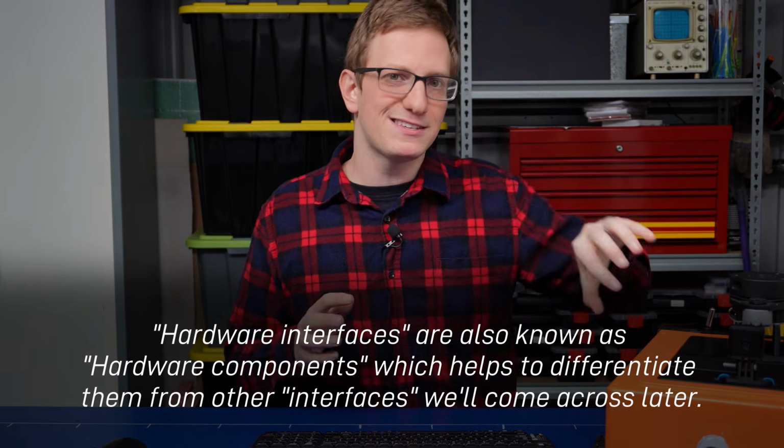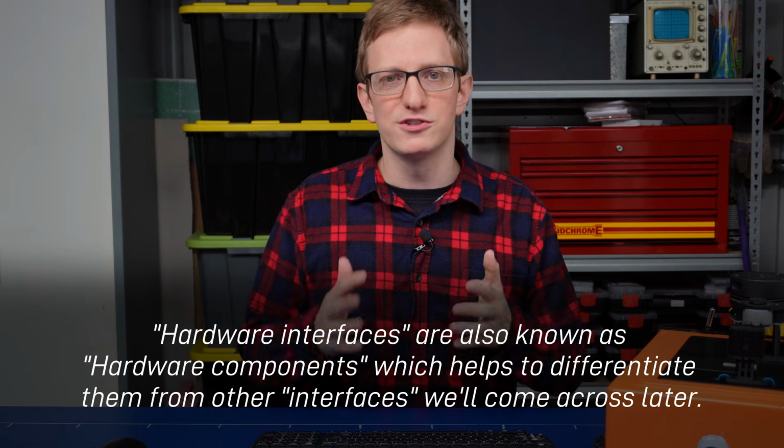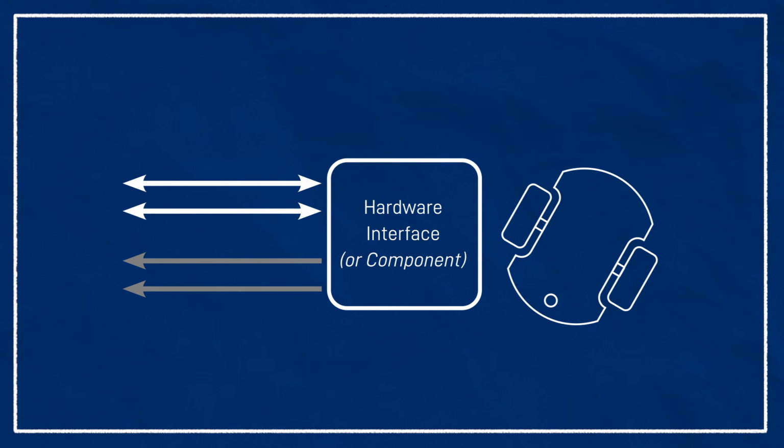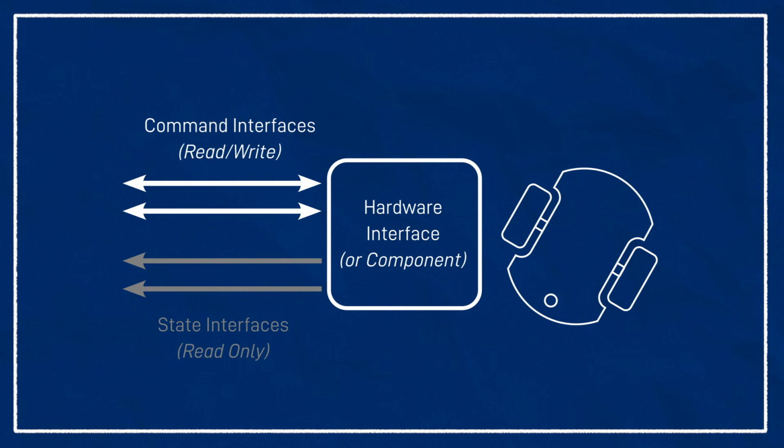To use ROS2 control with your hardware, the first thing you're going to need is a hardware interface. That's a little bit of code that speaks to the hardware and exposes it in the ROS2 control standard way. Ideally, if you've purchased a robot, then the designer of the robot will provide this for you. Otherwise, you might have to search for it online or write it yourself. If you've been following along with my build series, then you'll be able to use the one that I've written for this robot. Otherwise, like I said, you might have to write it yourself, but that's well outside the scope of this video. All we really need to understand is the way that it represents our hardware, and that's through command interfaces and state interfaces.